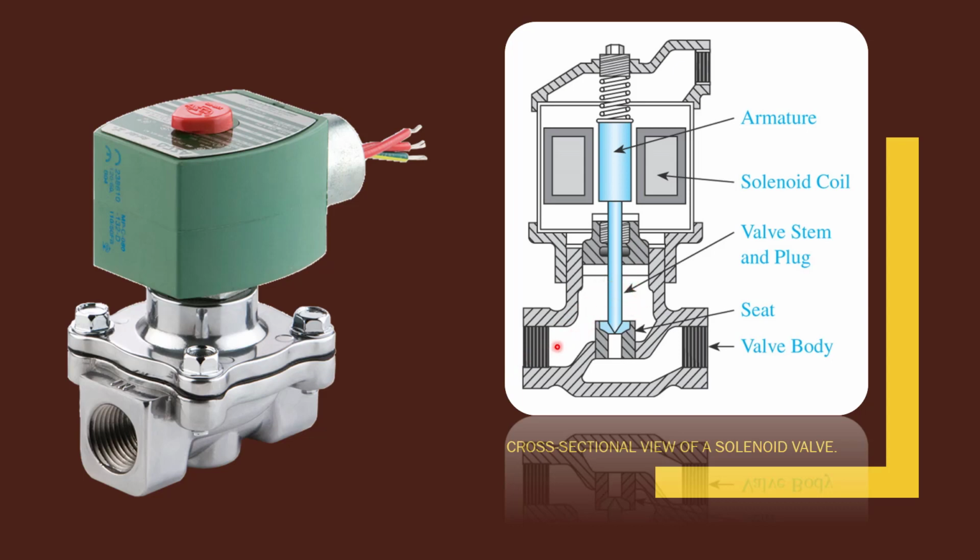So right now the gas enters this chamber and is restricted for any further movement, unless this valve seat lifts off of here, in which case this becomes open, and the gas can travel through this passage and then out the other side. So here is the valve, and we're going to operate it because it's steel. We call this shaft and the pin the armature of this.